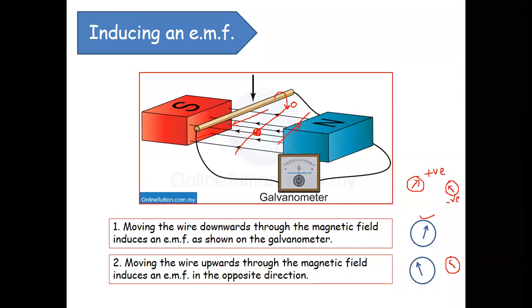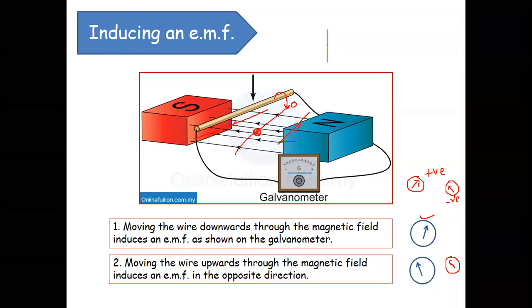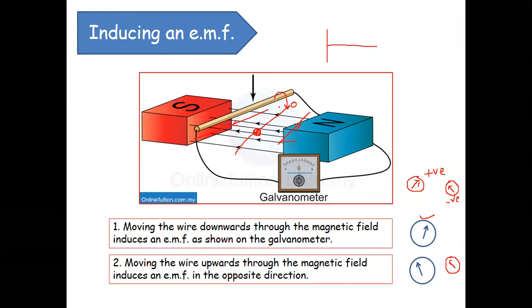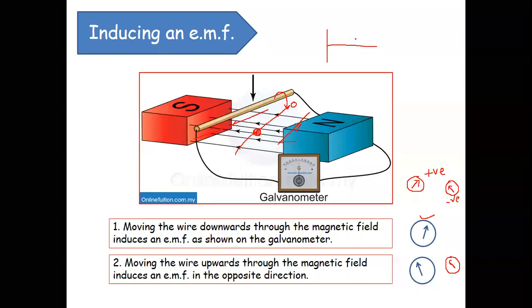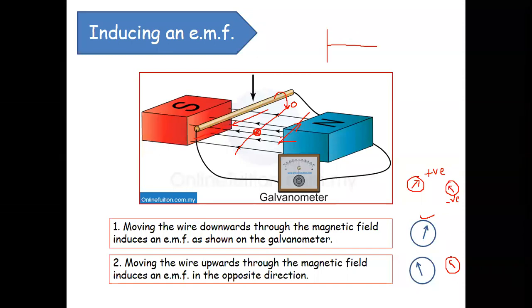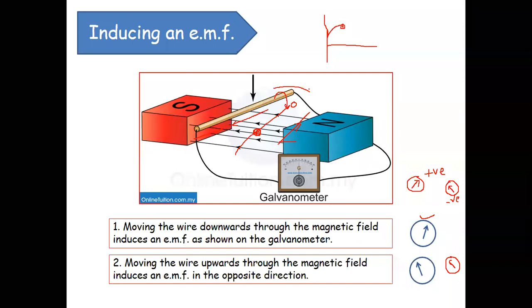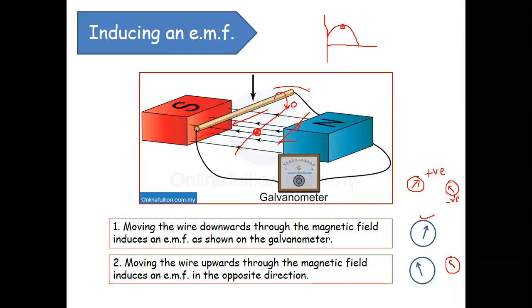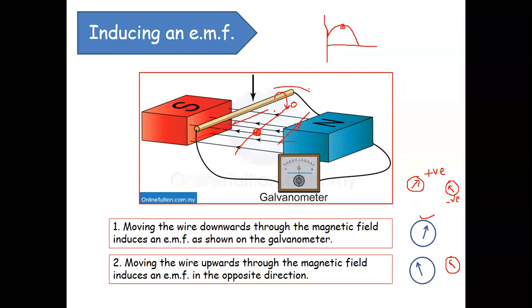When the conductor comes directly under the influence of north pole, positive voltage, and then between north pole and south pole, zero voltage. That means for one complete rotation, let us start from the middle of north pole and south pole. When the conductor is in the middle of north pole and south pole, no EMF is induced. When you rotate 90 degrees, exactly under north pole, maximum EMF is developed in the positive direction. When you move out from north pole, the induced EMF will reduce because the conductor is slowly going into the magnetic neutral axis after 90 degrees rotation.